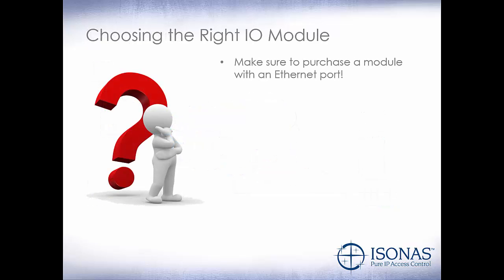Choosing the right IO module. First, make sure to purchase a module with an Ethernet port. There are some IO modules out there that still use RS-485, RS-232, and other protocols to communicate. We really need the Ethernet.